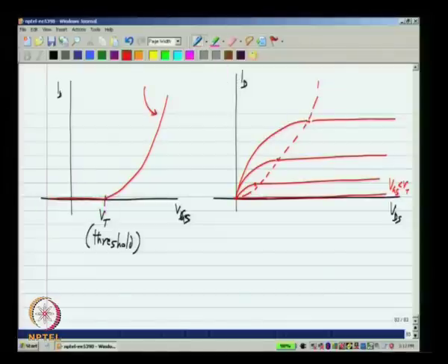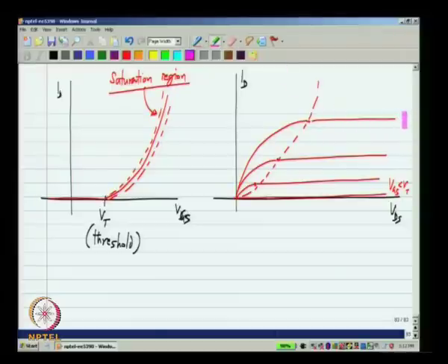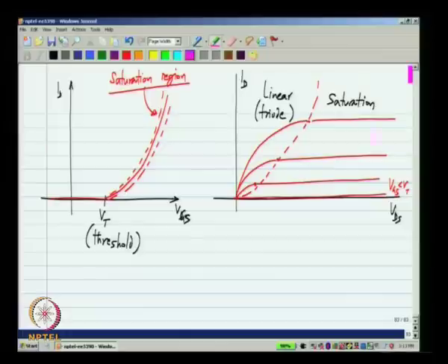By the way, this is the current in saturation region. Okay. Now, because it is in saturation region, the current does not vary too much with VDS. It does vary, but not greatly, because the slope in this region is very small. Okay. So, on this curve, this is the saturation region and this is the linear or triode region. Okay. I am assuming you are familiar with these MOS characteristics. I will only discuss things that are slightly unfamiliar from basic courses.